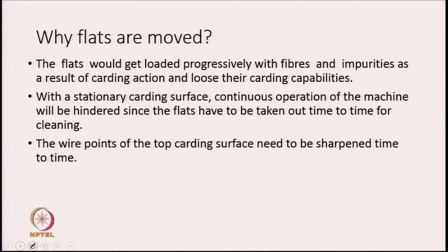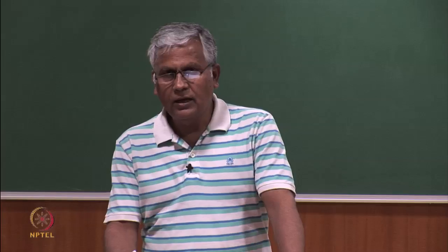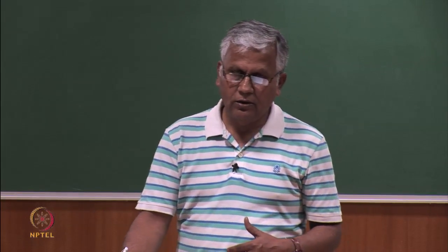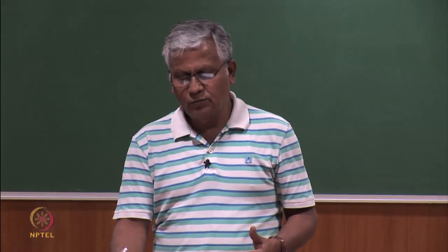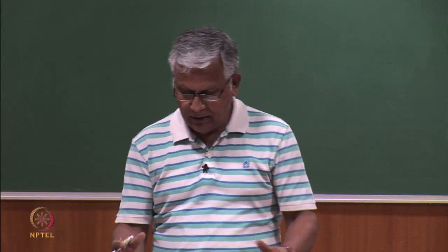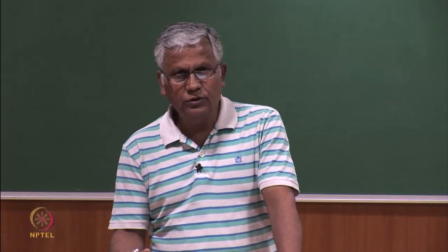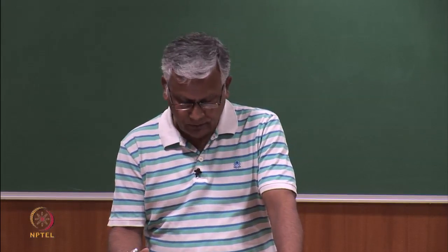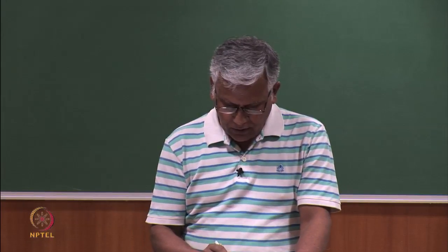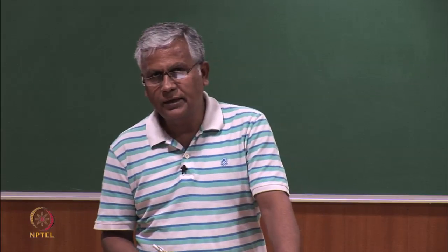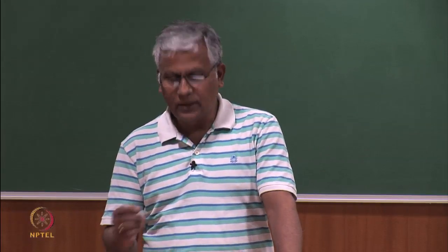The wire points of the top carding surface also need to be sharpened from time to time, because with time the wire points or the pins on the cylinder and the flats both get roughened, and therefore, we need to sharpen them from time to time, and for this also we need to move the flats, and actually you will see that we can then sharpen them when the flats are moving.